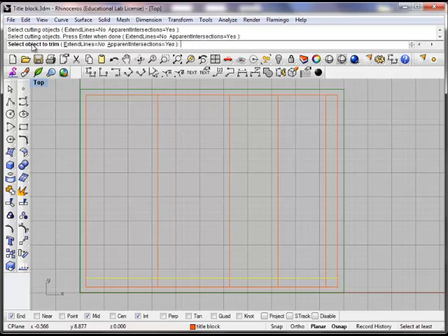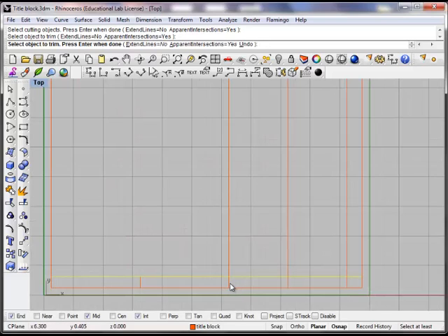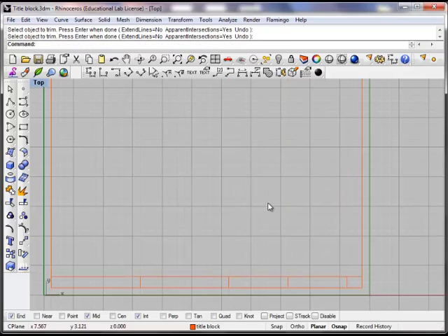Now what we want to do here is select the object to trim. Now we have 4 of those lines. You can do them, just pick it. What it does is it cuts it exactly back to where those intersect. Now if I wanted to cut underneath it, I could click here, and we're back and forth there. Obviously that's not right. Control Z will undo the commands. I can continue with trim. I'm going to pick here, pick here, pick here, and done. So hit enter, and I'm done with the command.